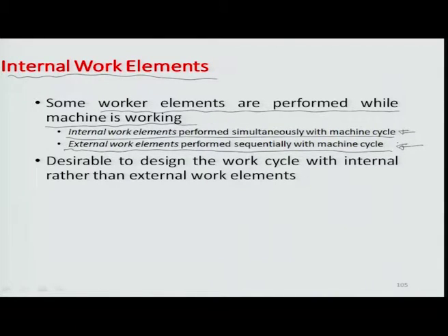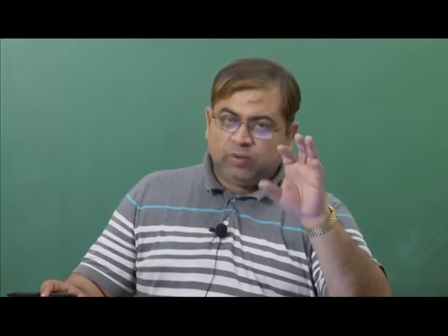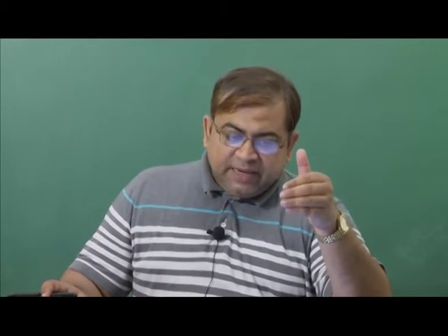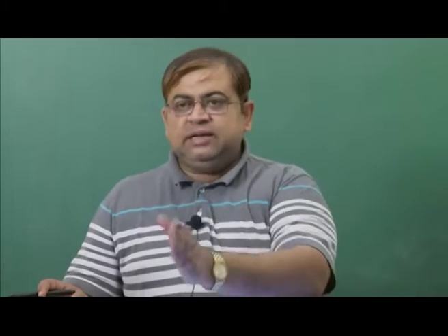Okay, so now if the machining cycle includes loading, unloading and the operation time, something like rework, which may come because of inappropriate machining, could be considered an external work element, because it is outside the cycle time. It happens on a one-in-100 basis, let's say, where you need reworking because probably a tool got damaged in that particular machine cycle or something happened, and it's quite random. It's not that it will crop up in every cycle. Okay, so in such cases, these are the external work elements which are out of the machining cycle, which otherwise includes only the loading, unloading, the inspection and the machining time.